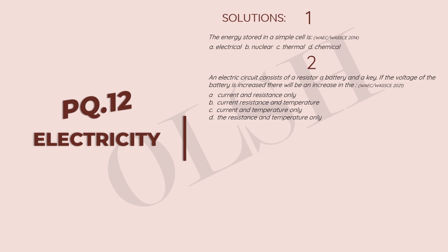Okay, so once you have an increase in voltage, you're going to have an increase in current, and what that's going to give you is an increase in temperature. And that's why if you keep increasing the current, most likely components are going to burn out. The reason is not directly that there's excess voltage on their terminals. No, it's because there's excess current flowing through them. That current will generate too much heat energy and will damage components.